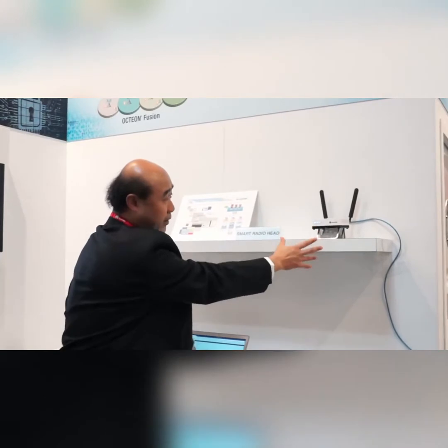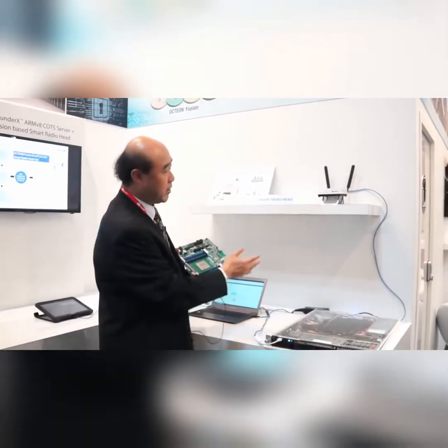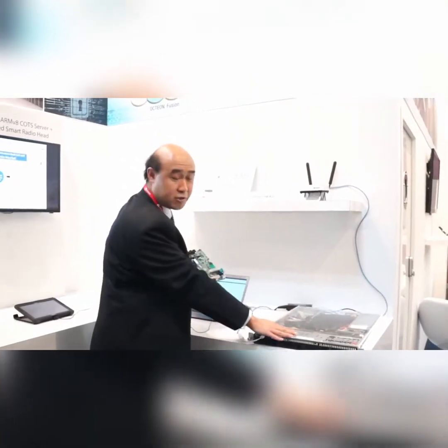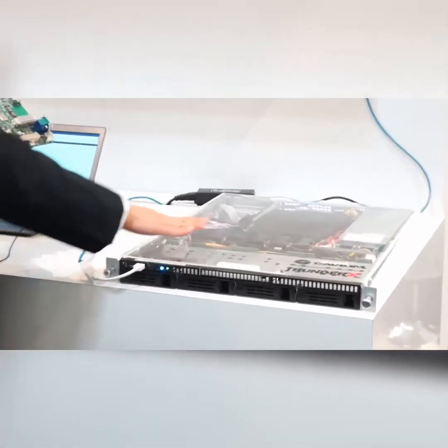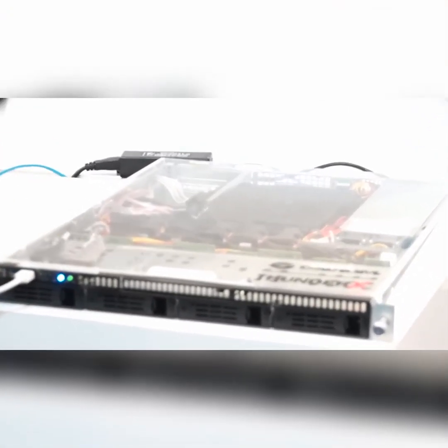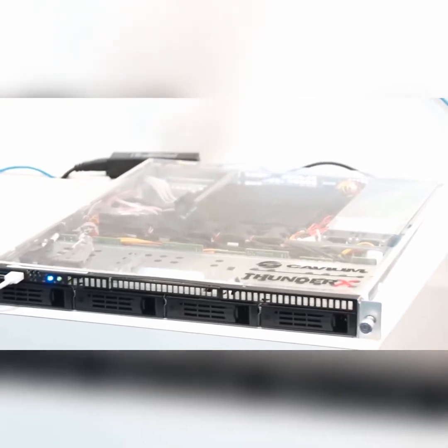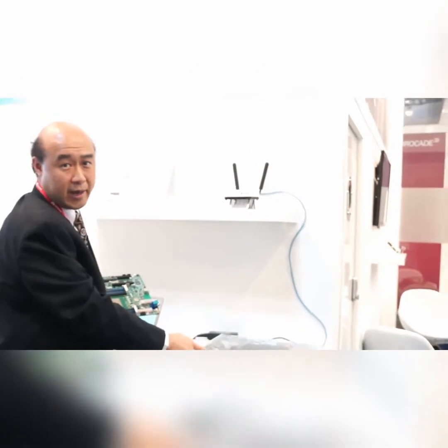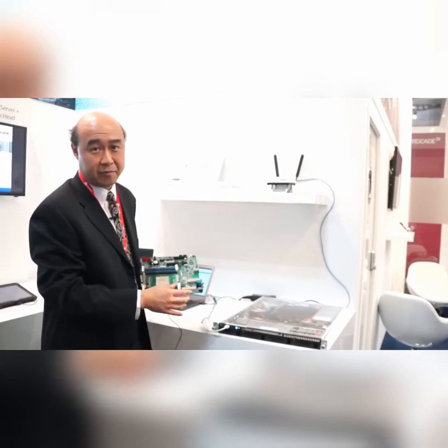In this case, it's a smart radio head, and it is very small. It's powered only by power over Ethernet, very low power. And the baseband processing, which is typically done by a base station, is split between a smart remote radio head and a centralized baseband processing. This system is typically called a Cloud RAN server. So when the traffic goes to the cell site, it is relayed to the centralized Cloud RAN server. In our case, it's only Ethernet, because that's a much more cost-effective way to do it.